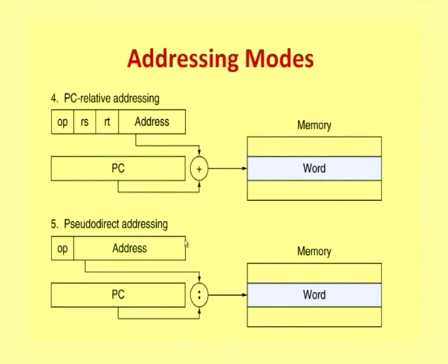So, with these different addressing modes, though we have looked at a large number of addressing modes, the number supported here is restricted, but with this you can pretty much achieve all the different operations that we have talked about. The advantage of restricting the addressing modes is that the representation can now be done with just fixed instruction words of 32 bits.